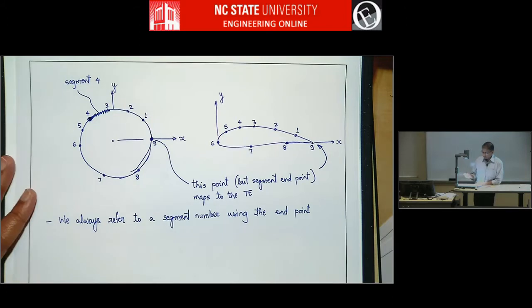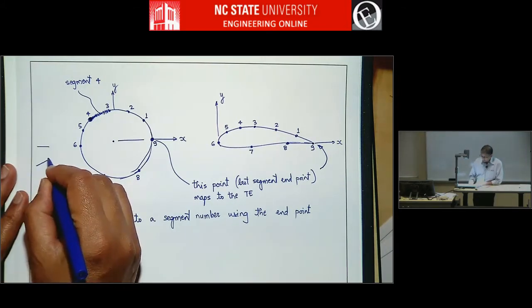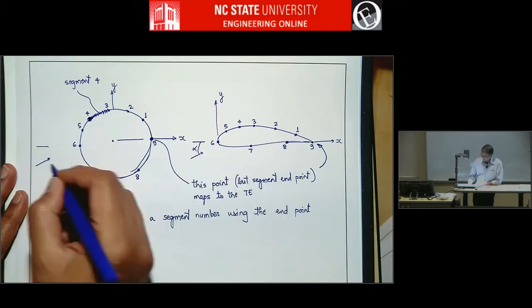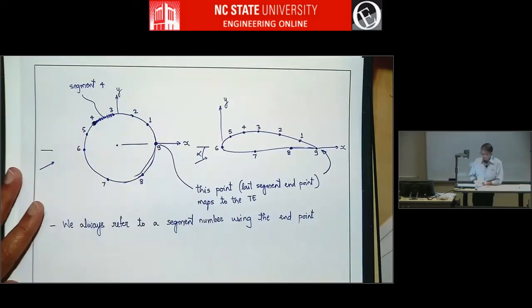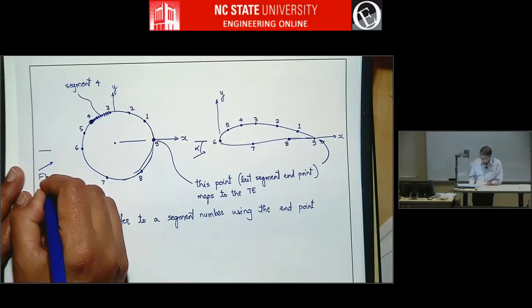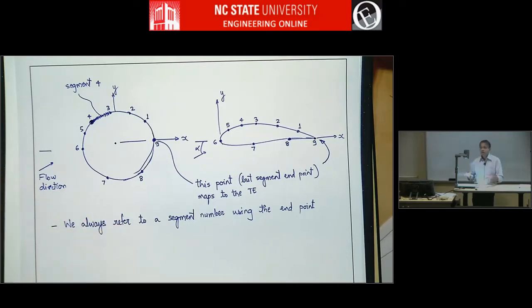And the way this works is, and we won't go into details of this, the airfoil, when it's operating at some angle of attack, in the mapping, in the circle flow, the cylinder will have some flow direction, and the conformal mapping will take care of mapping the flow around a circular cylinder to the flow around this airfoil, which is yet to be determined.